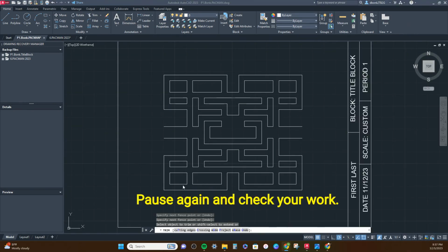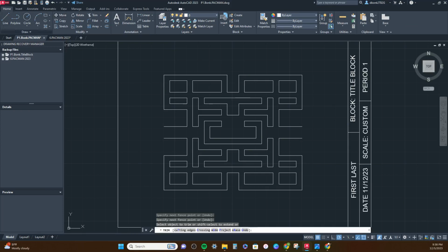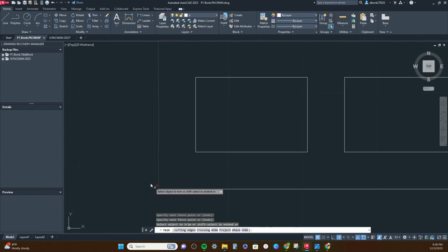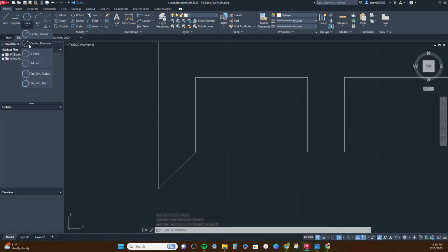And that's going to be another kind of patterning and tedious sort of step here, so just bear with me. You're going to zoom in relatively close, and you're going to turn the line tool on. So that works. Here we go. Point, corner to corner in here. Then we're going to use that line to create a center diameter circle.